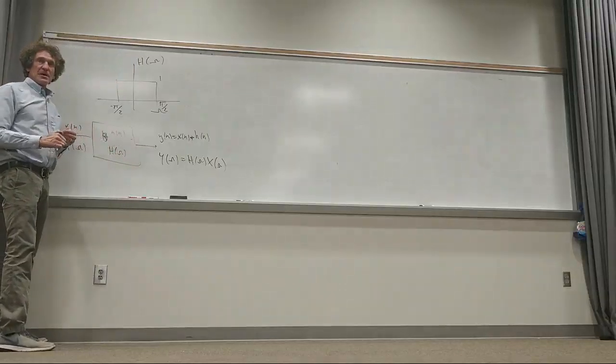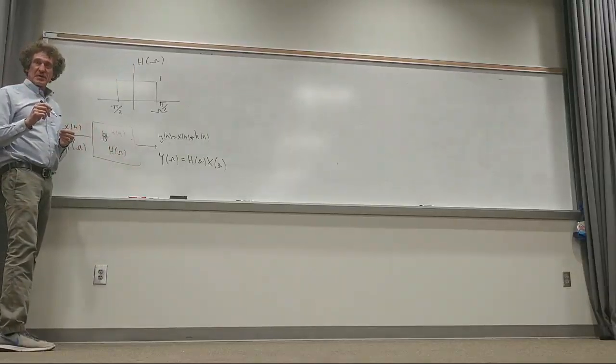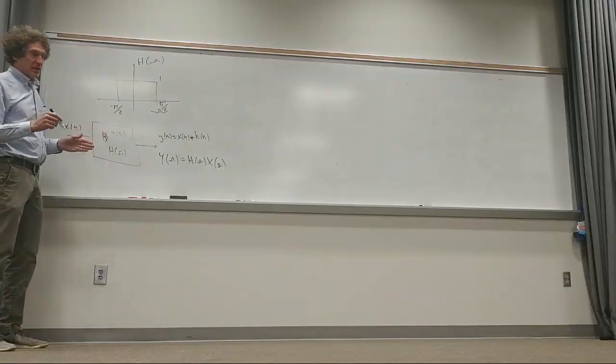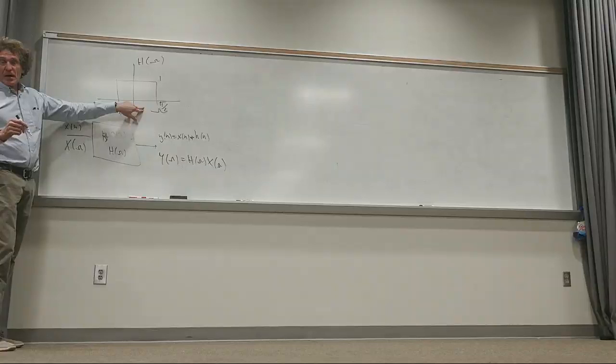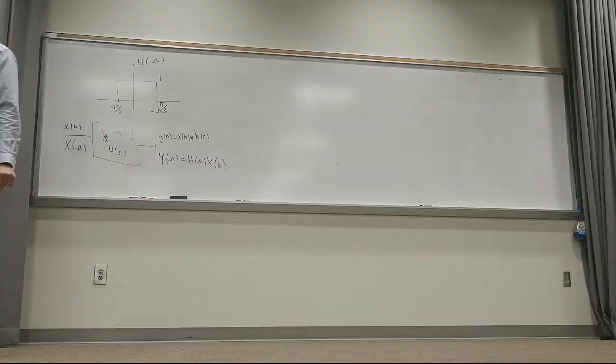That's the DTFT. You can get that by taking the z transform and just replacing z by e to the j omega, capital omega. Now, with this in mind, if this was a filter for the system, then I know I can get h of n. I can get it, by the way, for this one, we could use duality, couldn't we? You remember how if you were between minus pi and pi, the filter property, and you knew the transform, either forward or inverse of that, then we could simply use that to go ahead and get h of n, if we knew h of t for the continuous time. Do you all remember that class? I can go through that.